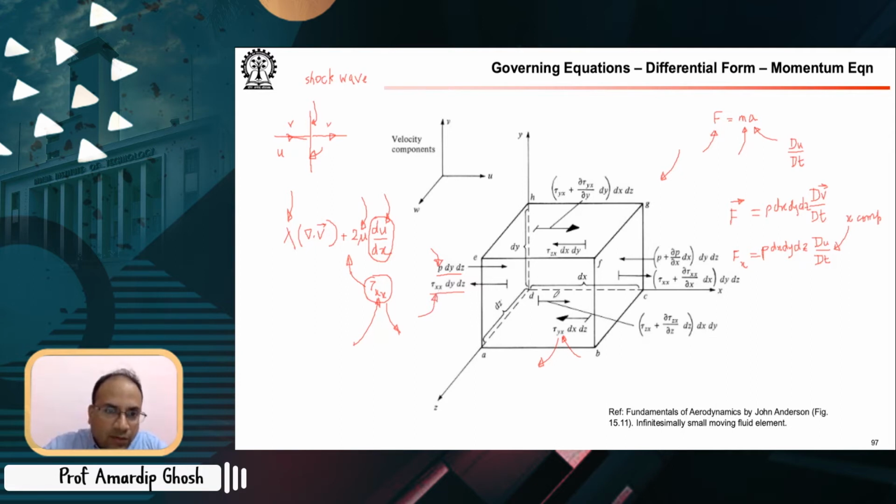So now you understand that the thermodynamic pressure driven force, P, is there. Velocity gradient driven forces are there, which are normal to the surface. Then you have the shear or the tangential forces. So here we are looking at all the forces that have some contribution in the x direction. So we are really looking at the x momentum equation, or the x force momentum balance equation.